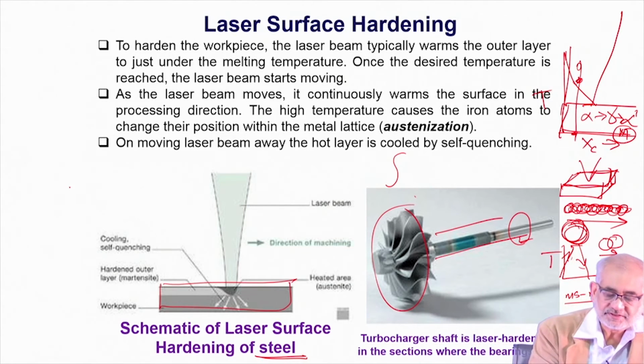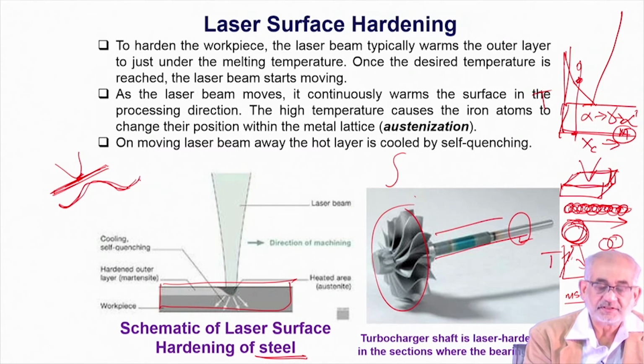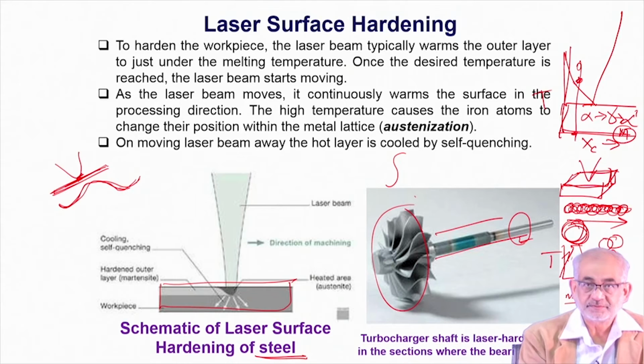The advantage of using laser is that if this is the surface we are talking about, and this is my beam diameter, I can make sure that the beam diameter at the surface is always in focus. If we are dealing with a curved surface instead of flat, I'll have to trace exactly this contour of the surface using a computer-aided mechanism, controlling the beam.